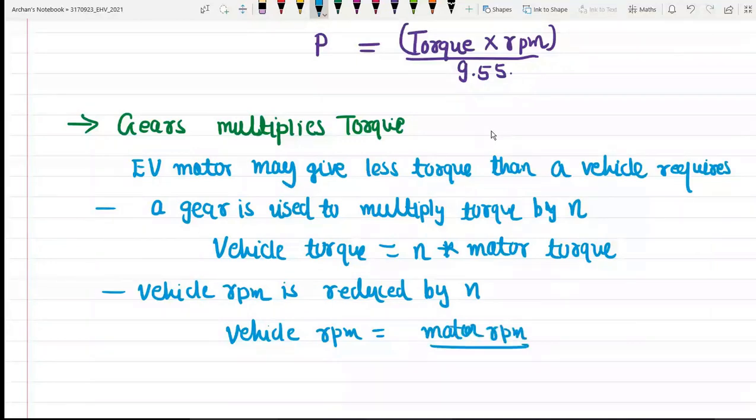Okay, so in the previous sessions of electric vehicle, we have seen the use of these gears, single gears as well as multiple gears, and how these gears are used to get the desired speed torque characteristics in case of induction motors, DC motors, or whatever motor we use, right? So whether we are dealing with battery electric vehicles or hybrid electric vehicles, gear will play an important role. But as we have seen, generally these electric vehicles use a single fixed gear only. These electrical motors are usually designed to work efficiently over a large range of speeds and torque, and this is the reason why a single fixed gear is normally used. That would be the preference, as long as one can meet all vehicle requirements with the motor and a fixed gear.